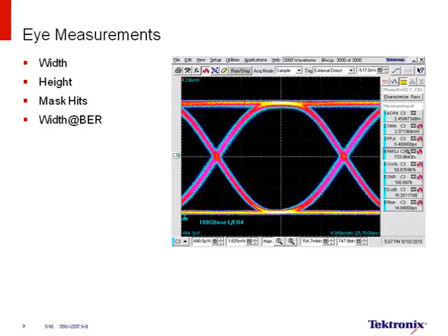Now the next question would be, well, how do you determine what the setups are? The best thing to do, if it's available, is to ask for these settings from your silicon vendor. The next best thing to do is use the standard setup. Many of these applications will actually set these up correctly per the standards requirement, because the way the standards work is that these are minimum requirements, and very often the silicon vendors implement clock recovery that goes beyond the minimal requirements.